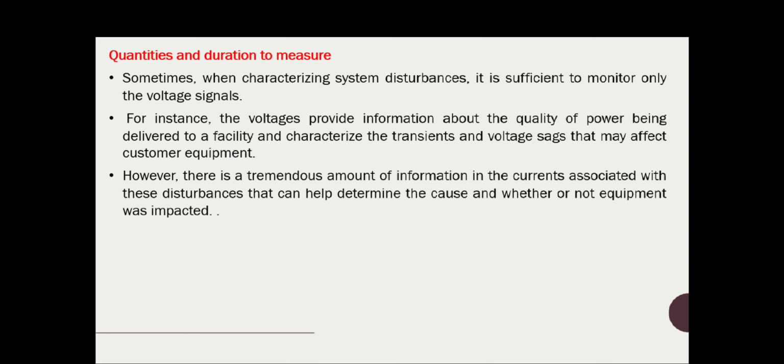So before going to monitor the power quality issues, it's better to identify which quantities and duration to measure, whether we need voltage or current quantity, etc. Current measurements are used to characterize the generation of harmonics by nonlinear loads on the system. Measuring the voltage alone is not sufficient to characterize the harmonic impact caused by nonlinear loads.